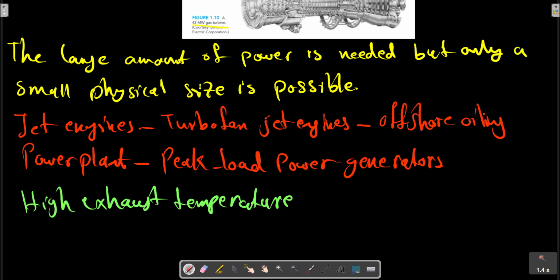In the example mentioned previously, the jet engine and the turboprop applications utilize part of the power to discharge the gases at high velocity. This is what generates the thrust of the engine that moves the airplane forward. The gas turbines in this application are therefore designed differently than those for the stationary power plant, where the energy is released as shaft work to an electric generator.